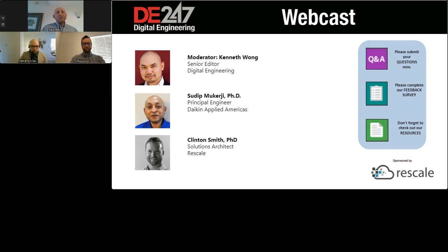So that means smaller compressors, smaller diameter piping, smaller sized heat exchangers, smaller diameter fans. So, less weight, smaller units. That means we have to ship things that are much lighter. So overall, all around, it's a very green story. But it also means that we have to do a lot of HPC computing work to resize and redesign our products to handle this new refrigerant.